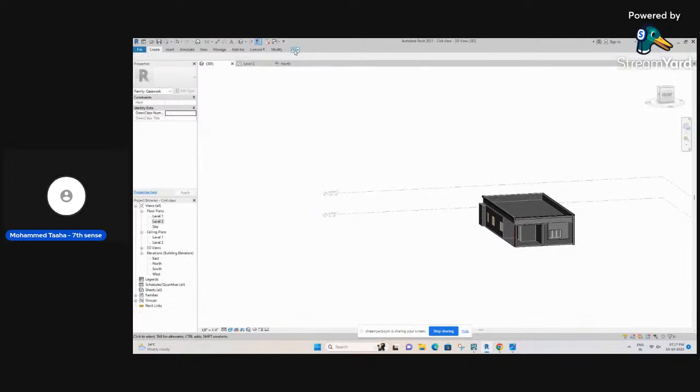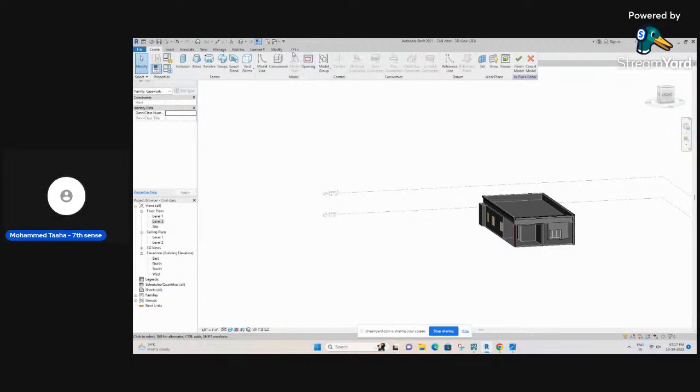So another key point to remember, sometimes accidentally this button is going to be clicked. This represents show full ribbon. When you accidentally click that, all the tools disappear from the user interface and you can only see a few tools. But if you want all the tools to be visible all the time, you need to click on this symbol, which is represented with show full ribbon.